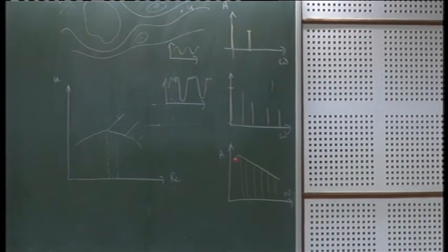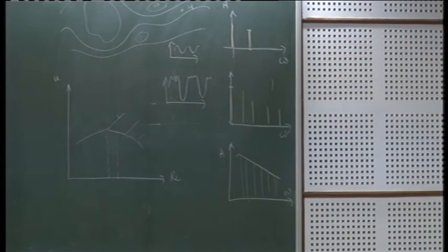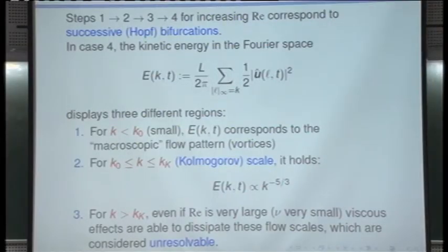And instead of plotting the spectrum in time, what I have written here to explain the situation is the spectrum in space of the kinetic energy. What is the kinetic energy? Essentially the L2 norm of the velocity, up to the density, okay? The energy per unit volume, by the way. So this is the L2 norm of the velocity, and since you know that the L2 norm in the real space is equal to the L2 norm in the transformed space, in the Fourier space, that's the L2 norm of the Fourier transformed velocity, but in space. So that's the Fourier transform in space.